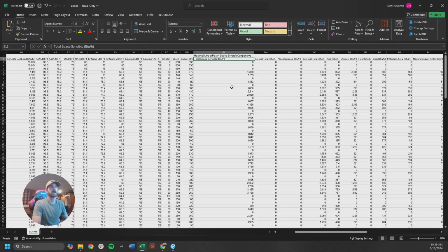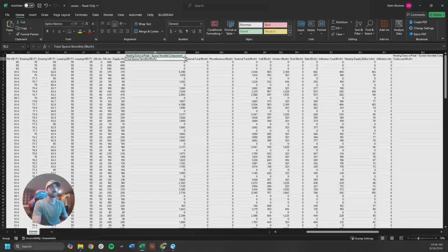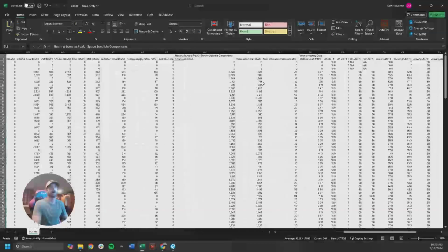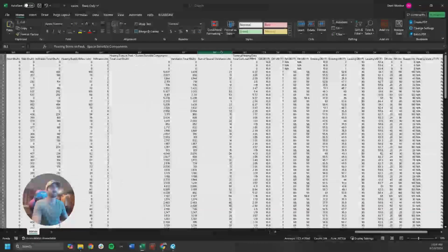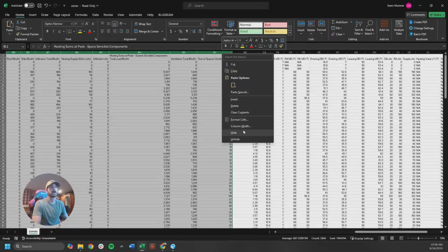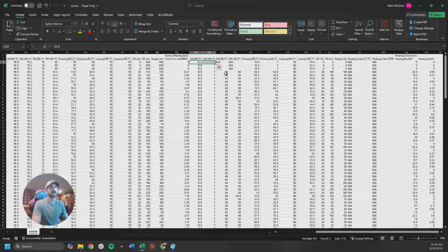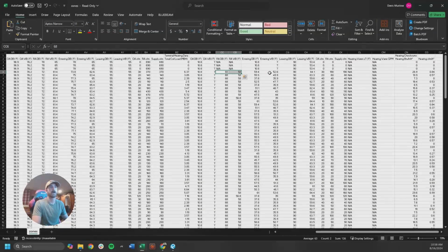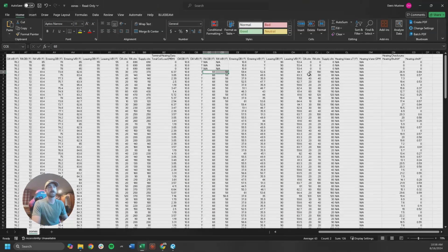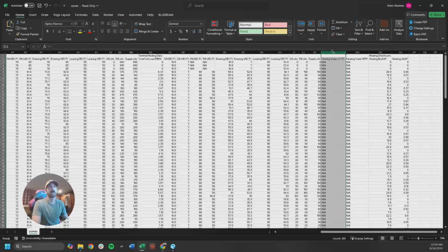Then I've got my heating. Again, this is a breakdown of my sums at peak, and I really want the coil data. So now I have my heating coil load with the outdoor air information about that, return air entering, leaving, all that good stuff. This is in heating mode, as well as the CFMs for that. So it'll show me my heating supply CFM as compared to my cooling supply CFM. So I like having that.